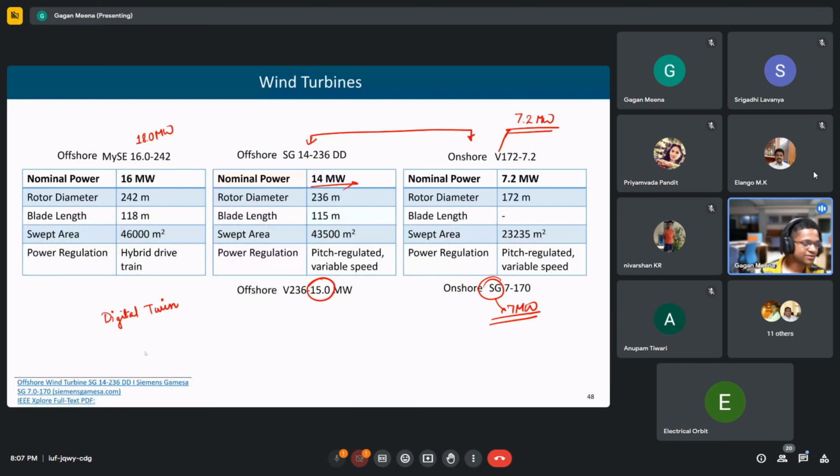Depending upon location it may vary, but it is there at night also. So a solar and wind hybrid plant can also produce during evenings and night, and can help us meet the evening peak demand. That is a good option, and if storage is combined with that, it can provide other types of services also.